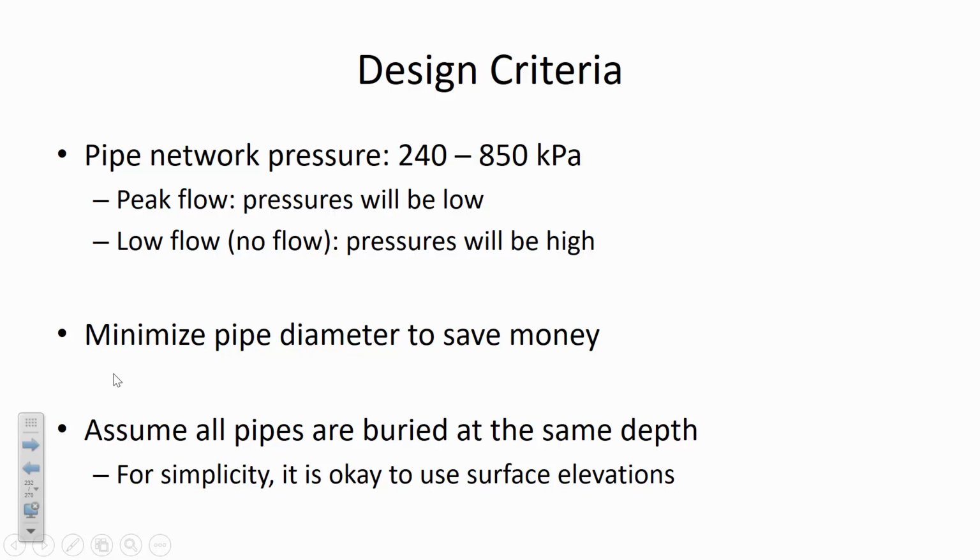When you think in terms of the energy equation, that's what WaterGEMS is going to be solving. And so for it to tell you what is the pressure at any point in the network, it's going to be calculating the head losses, it's going to be calculating local losses, it's going to look at the elevation difference, it's going to know the flow velocity. So all those things are going to be taken into account when it calculates the pressure.